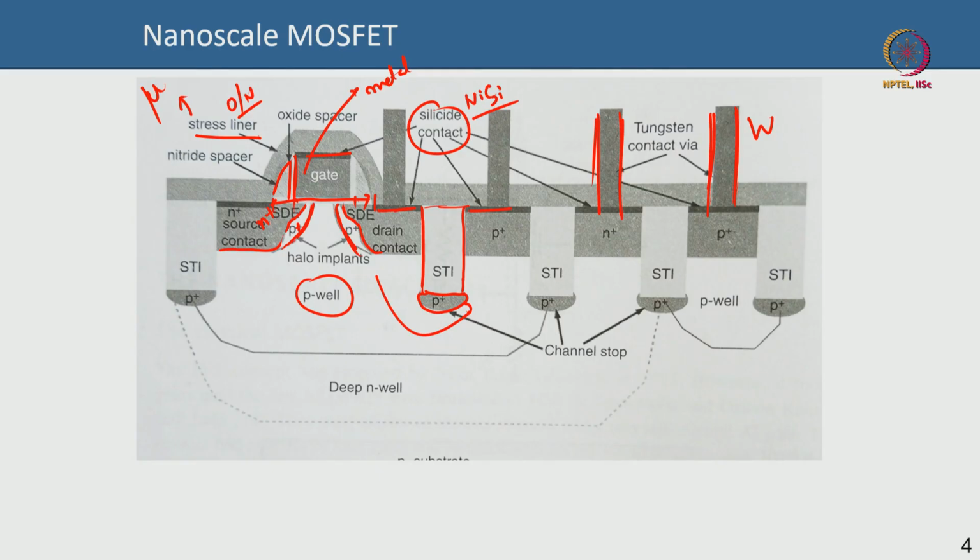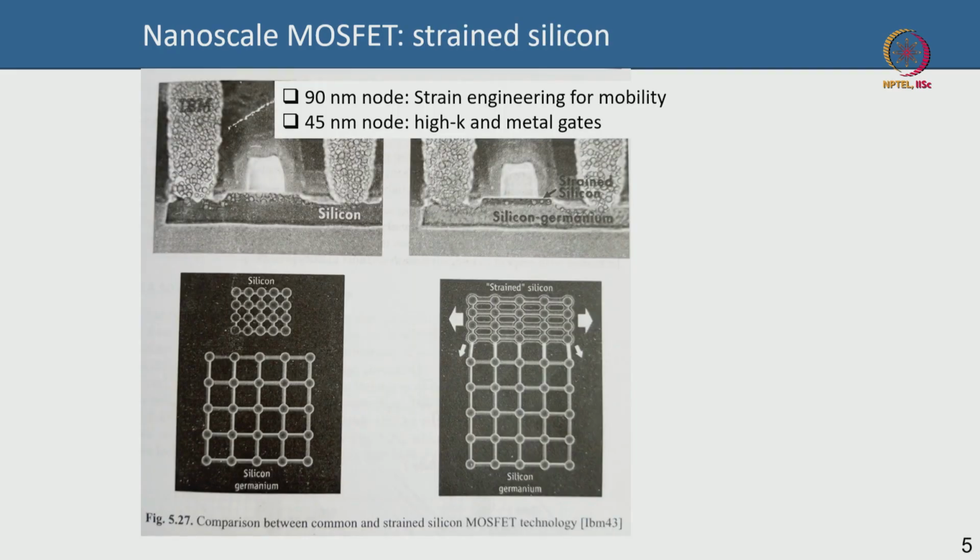When I am talking about RF application in the context of silicon nanoscale or highly scaled planar bulk MOSFETs, here we are typically talking about low power, low voltage application, which is very enormous in number and scope. All kinds of mixers, oscillators, phase lock loops, frequency synthesizers, anything in the RF domain which is low power, low voltage on a circuit level, you need so many of them. You need an oscillator, you need a mixer, a lot of times in all these circuits. So you can enable them using this kind of planar bulk CMOS based process, MOSFETs. You can implement them.